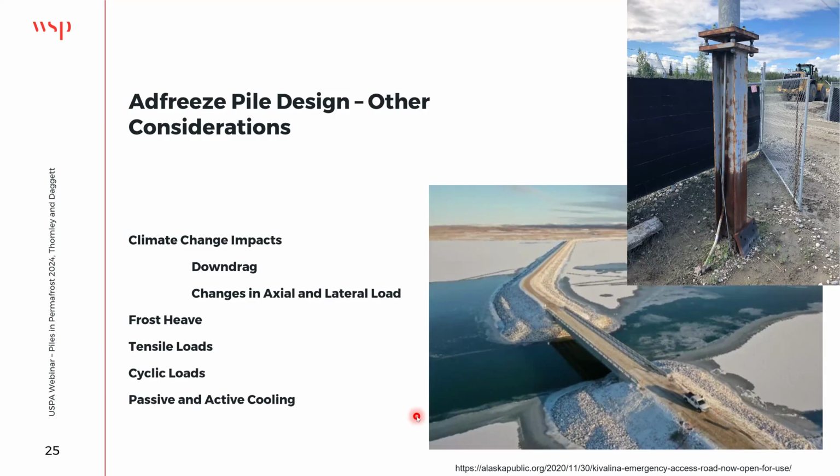You can see where the paint was painted at the ground surface back in the day, but that pile has since jacked over time and essentially wasn't long enough to resist the frost jacking forces that Andrew mentioned before. And you can actually see the conduit that's being ripped out of the ground as that pile continues to jack into the air.